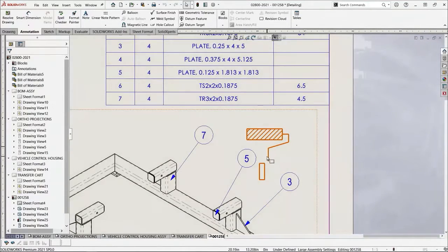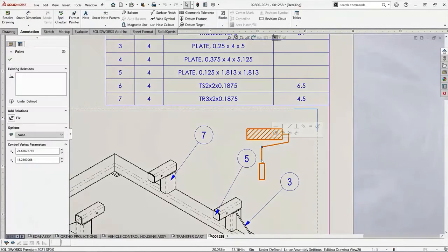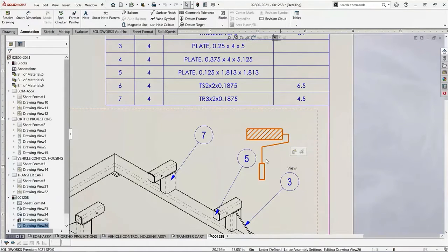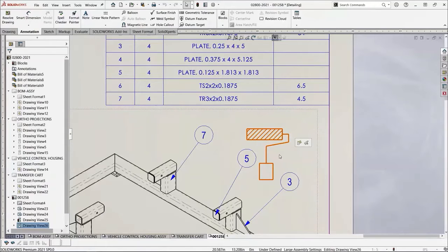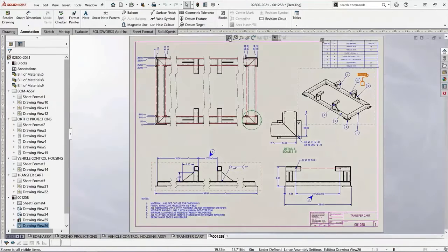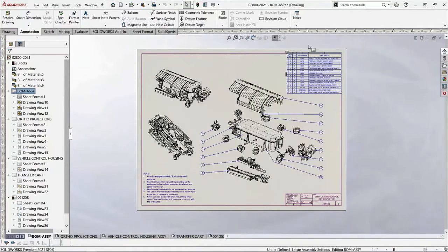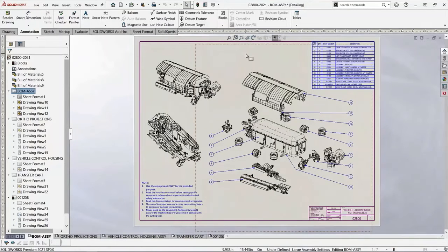Here's some sketch geometry in this view. Oftentimes previously, relations on sketch geometry and views would be incomplete, or you couldn't use all of them. Now in 2021, they all work. Notice that it picks up the automatic centers of items here, and even the relation to midpoint of the lower line gets fully carried through in the drawing view and sketch arrangement.